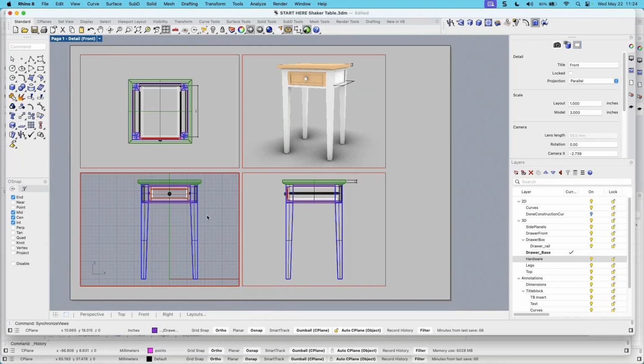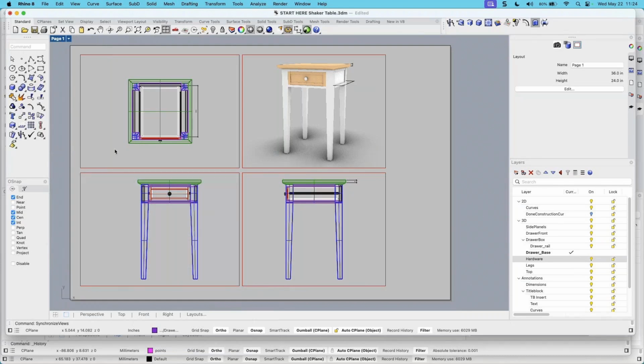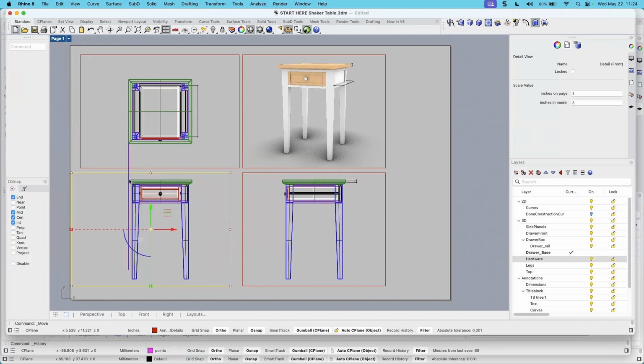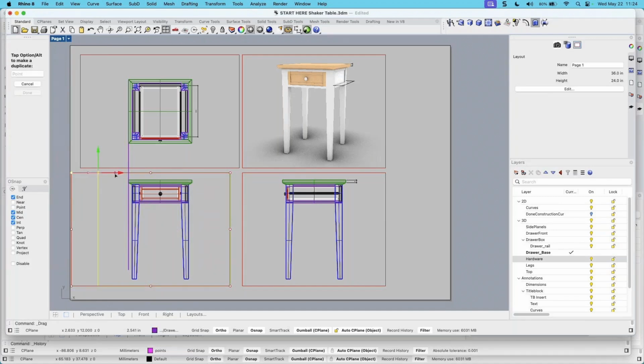Now, during the GoTo training broadcast, I don't have a lot of really good luck with this. It seems like they always are off. If I do this after class, they come out great. But anyway, you can see these two aren't lined up. So what I may want to do here is move and grab the endpoint and then move it over to that line. Okay, and then I would have to grab the control point, just one, because we're restricted to rectangular viewports. So you can't make an irregularly shaped viewport.